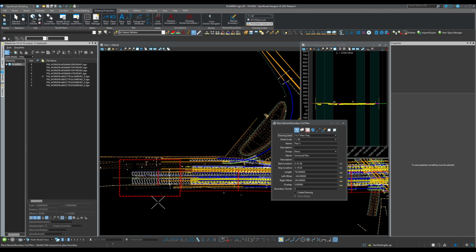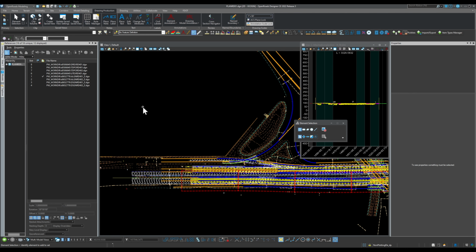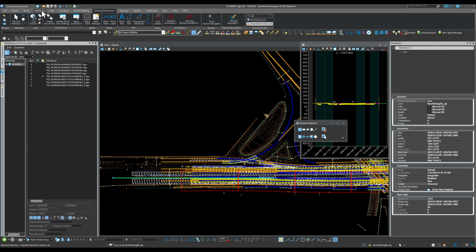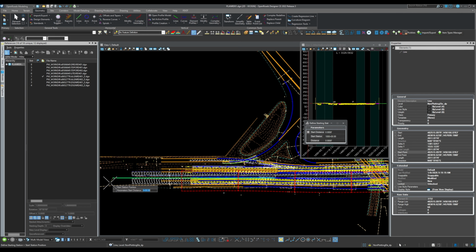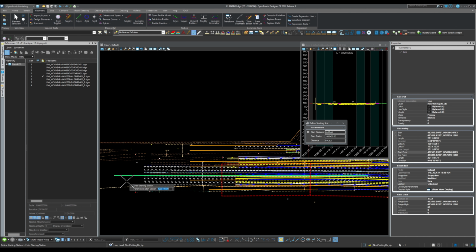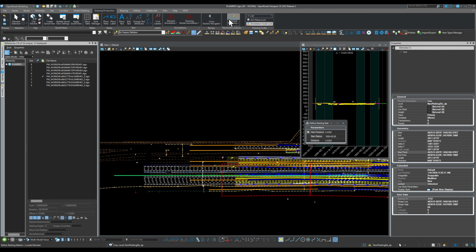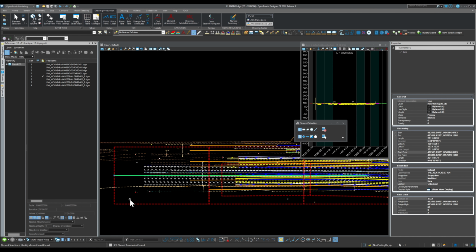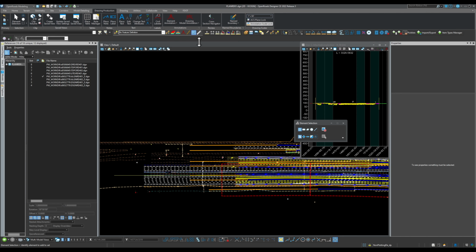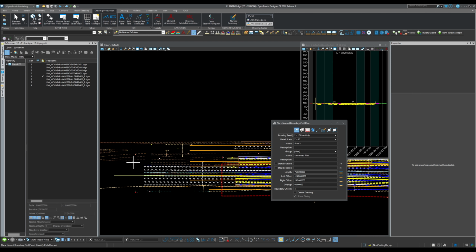So my trick for that: either leave it like this and don't care about it, but if you're still anal, after you draw this, you can still go to geometry, then start station, and you can add a station to this line. For example, you want it to start at 1,000. And now let's go to draw and production, and let's click on it. Oh, too fast, I clicked too fast. Let's go back here again. Here you go. As you can see right now, it's reading the station that I just added to it.